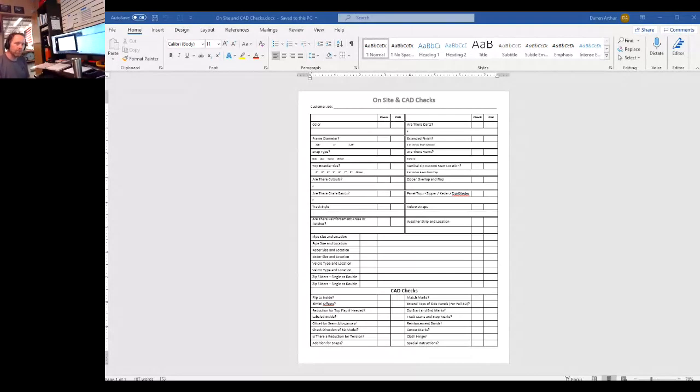And what had happened with this model is I didn't check. It flattened to the inside, which is how we work. But normally it flattens to the outside, and then I would flip or mirror that project. Because I didn't do my direction check, the entire enclosure was made inside out. So we're talking a 3-second command to save a week's worth of work, right?